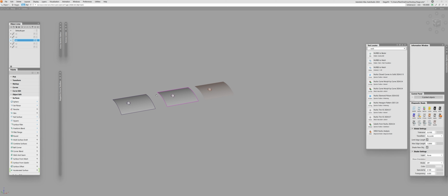And by the way, if you're watching this and you're on the Alias 2025 educational license, you're out of luck because it doesn't have any exporting options because, well, it's just for learning, right? So the alternative to trying to export using the native tessellator and exporting options within your CAD software package is, as I said, to use external tools.